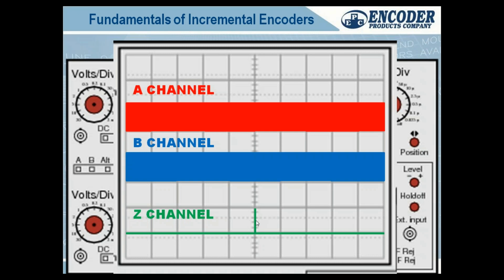If you put an incremental encoder on an induction motor, I encourage you to get it with a Z, because what the VFD will do is, if we know we have 1,000 pulses on this disk, well, then we know that every time we see Z, we can reset an internal counter, which is what they do in the VFDs, and we should count to 1,000 before we see another Z.